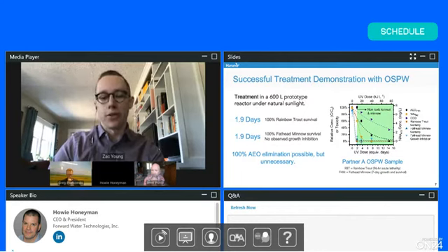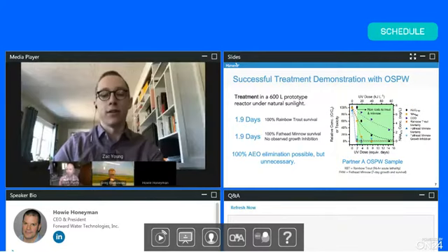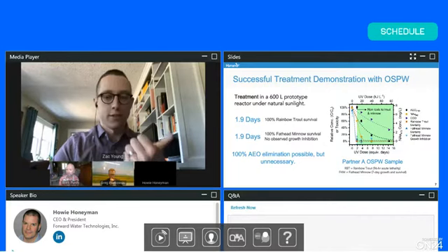And this is where we were able to demonstrate that under a couple days of sunlight, which conveniently in an area where we were seeing is quite similar to the typical sunlight exposure and intensity in Alberta as well, we were able to eliminate measured toxicity on rainbow trout and fathead minnow bioassays, which are 2 of the standard assays used for evaluating water quality. And through that process, we're able to eliminate toxicity without necessarily fully degrading or eliminating those acid extractable organics and naphthenic acids.